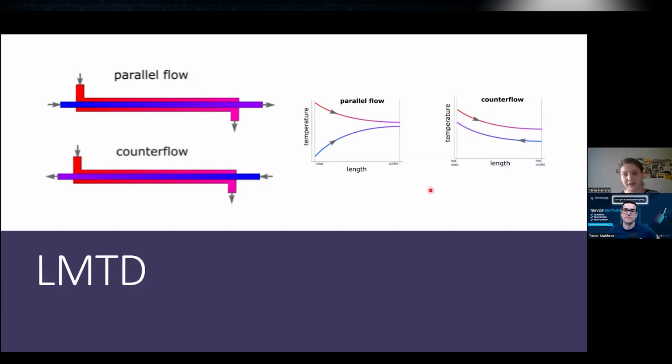This is something general, but it depends on the type of heat exchanger and also the refrigerant or fluid. But counterflow heat exchangers generally have higher efficiency because they maintain a larger temperature difference between the fluids throughout the heat exchanger.